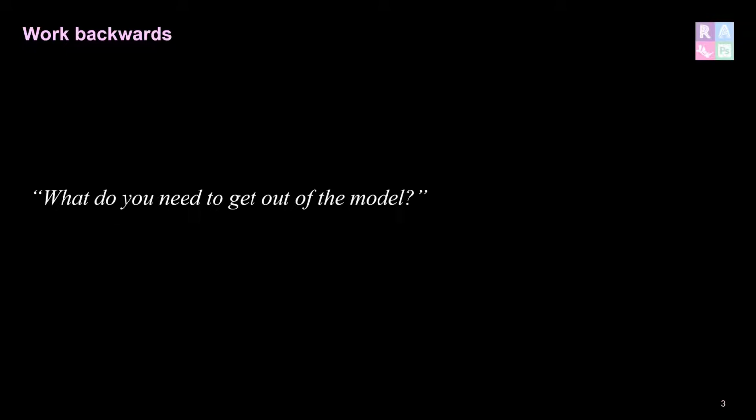There are other instances where you need to get strong amounts of metadata out of a model. So if you pick a manufacturer in that instance, you may be better off, because you might have a generic box that is a dishwasher, but it could be a Fisher & Paykel dishwasher, or it could be a Samsung dishwasher. But if you download the manufacturer's dishwasher Revit family, it will give you the serial number, the warranty period, the contact details, maybe the cost per unit, stuff like this. So it really helps to work backwards in terms of what you want to get out of the model, and then that helps you understand which way you need to go.